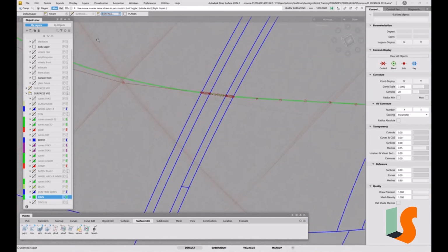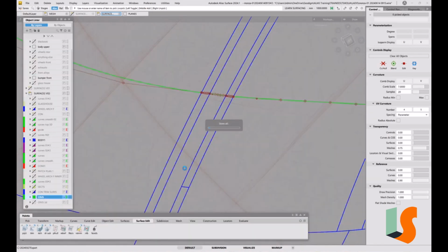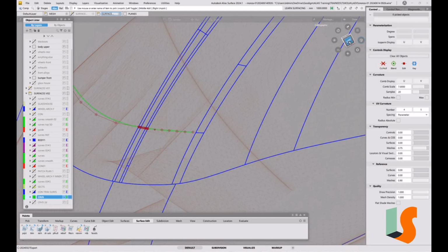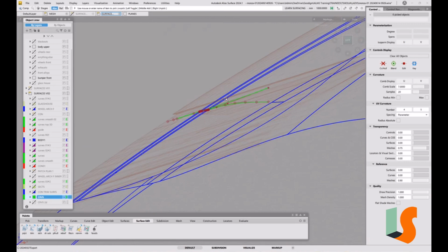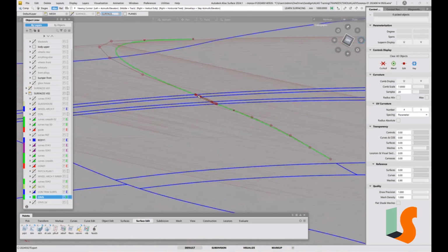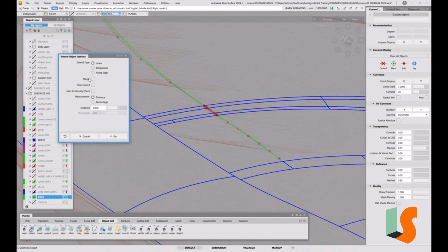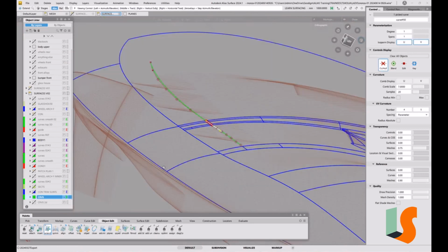But I'll try the same trick again of putting in that line, and then trying to build a solution that's a little bit better than that. Because if I look at that from the side, when we're dropping that down in the Z direction, it's such a slope there that really that's probably not the direction to drop it in. Now I put it in a straight line before. I'm going to do that again. So I'm going to use Object Edit, extend once more. So linear, no merge, just to give me that straight line off the edge as a separate element there.